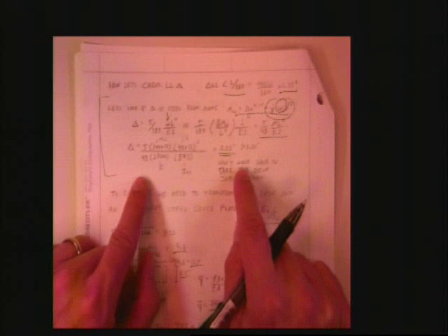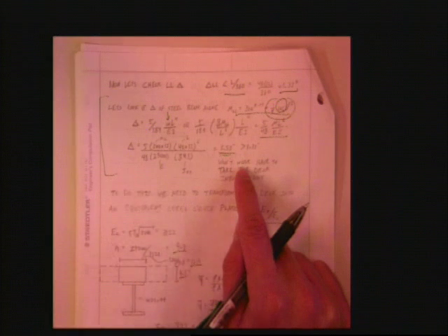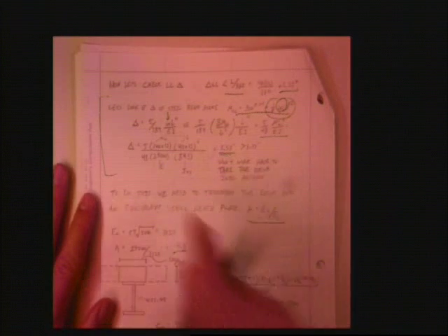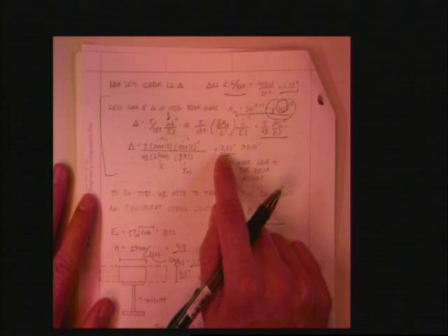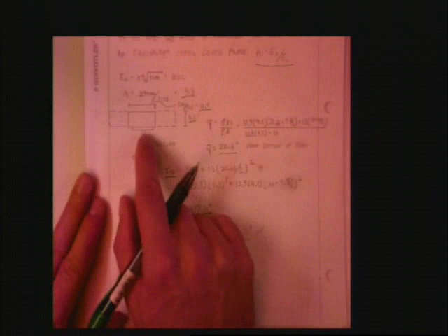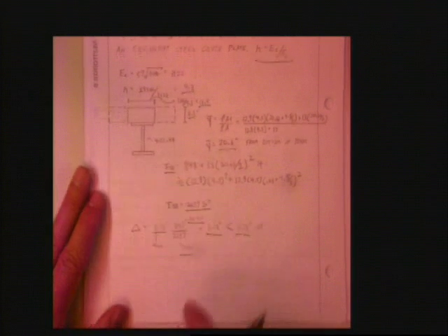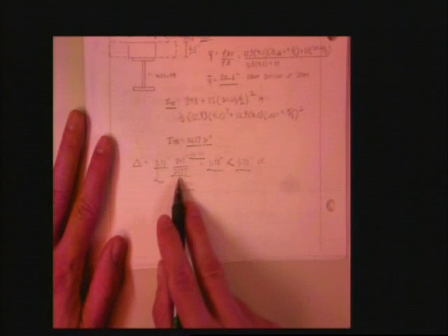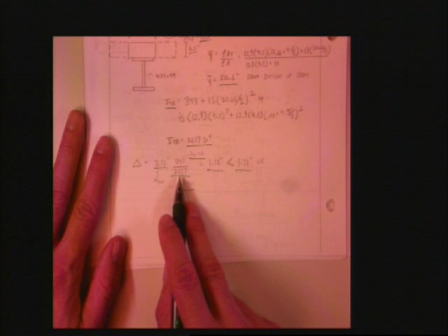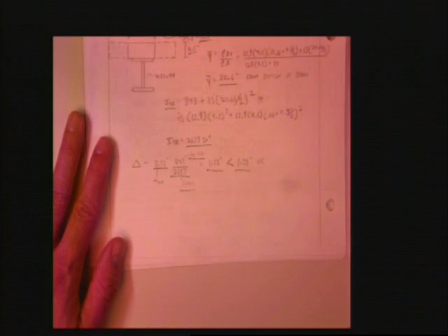Now please realize, you don't have to do this if you don't want to. Okay? This is done more for illustration purposes, to show that we don't get near the stiffness out of just the girder as we do with slapping this deck on top. You get a lot more stiffness. You get a lot more I. Look at this. It's way more, right? It's 4 times as much, right? So you get 1/4 of the deflection.